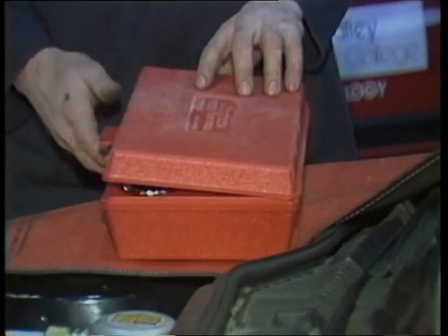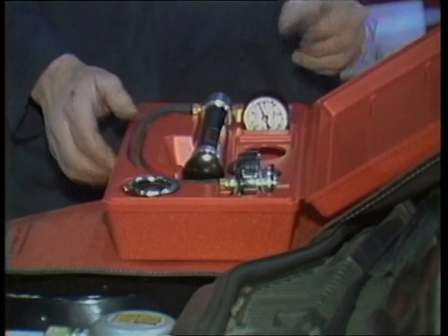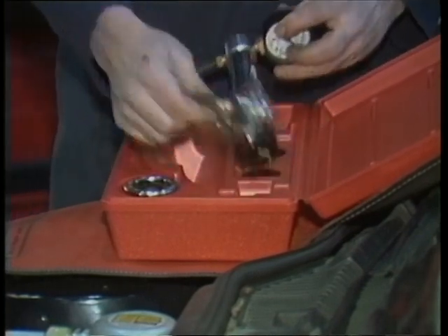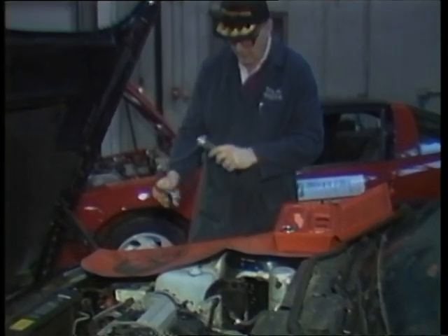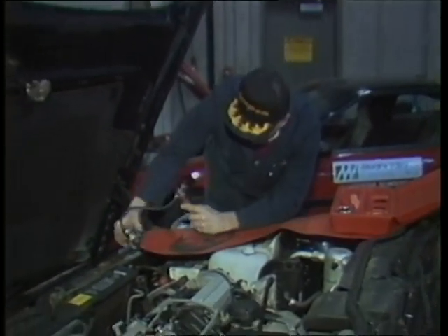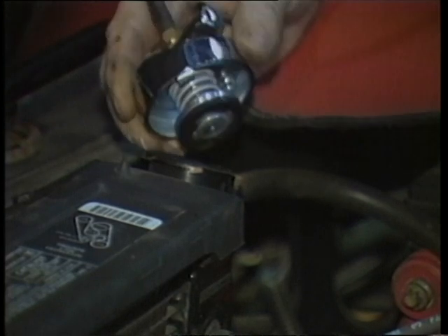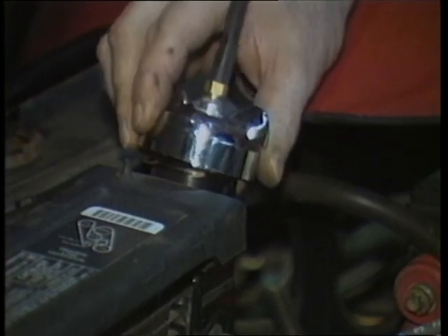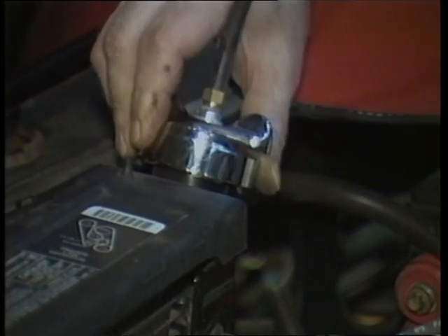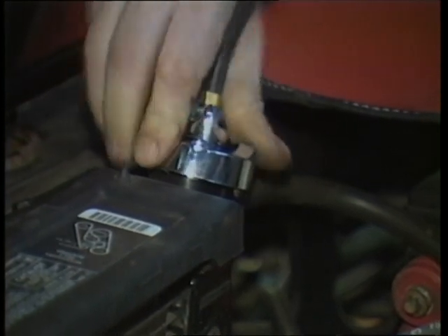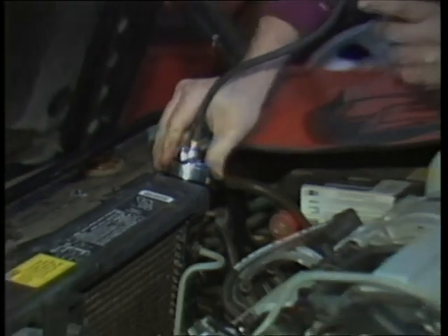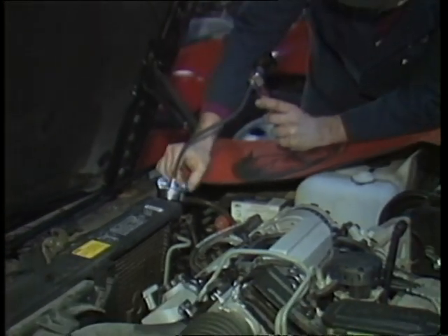A pressure tester is commonly used to check the system for leaks. It will check the radiator, hoses, freeze plugs, and other components for ruptures. Remove the radiator cap and install the special tester cap over the filler neck. Push down hard while turning. Pump the tester handle until the pressure gauge reading equals the system pressure rating.